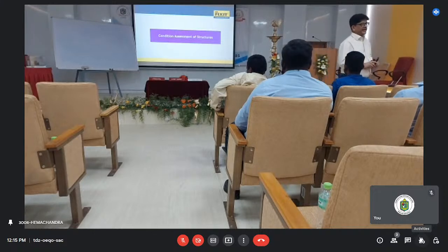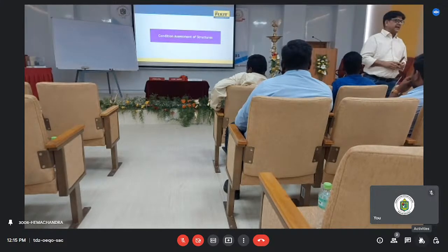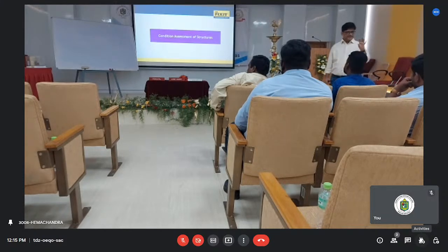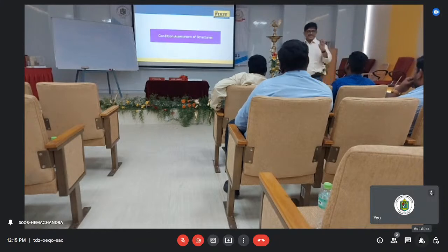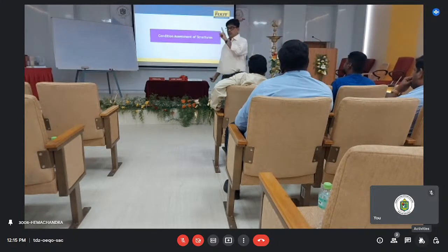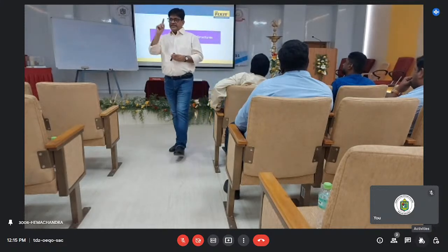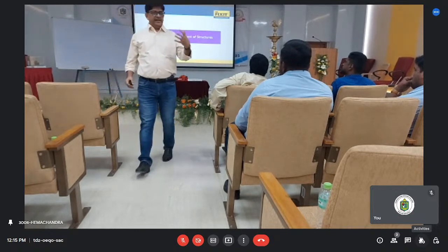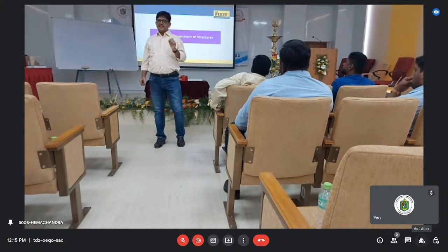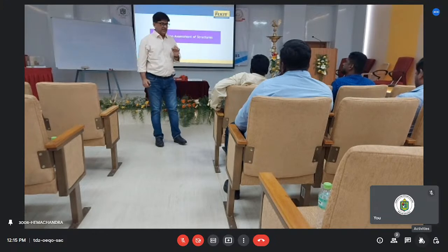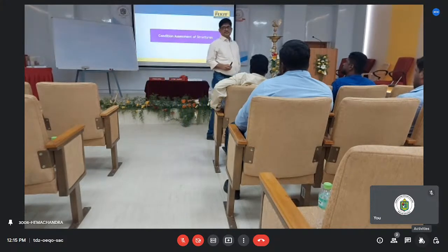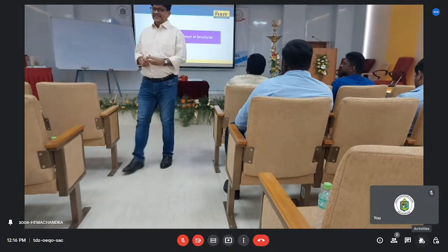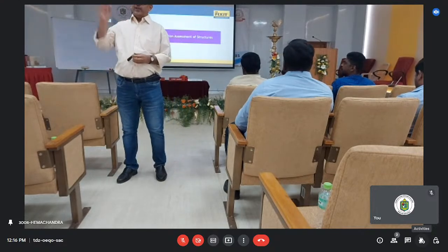First of all, you have to locate and visually observe where from it is happening. That should be the first thing. So you have to first get a checklist and understand where the actual problems are. Is there any other effect outside, on the roof or anywhere? So the actual location of the problem. Next, the source. You have to find out the source, the path leading to it. If you have found the source, everything is solved.